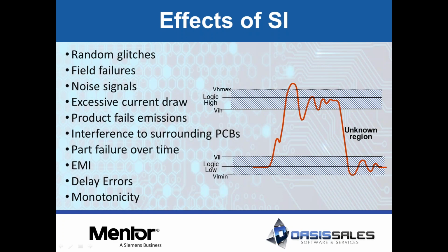So what are the effects of signal integrity problems in your design? The biggest thing is that you're going to have a hard time figuring out why one of your designs may not be working. And it could very well be induced by signal integrity. So random glitching could be occurring, data rate failures, data errors when you're doing your testing can all be induced by signal integrity, and you may or may not realize this.